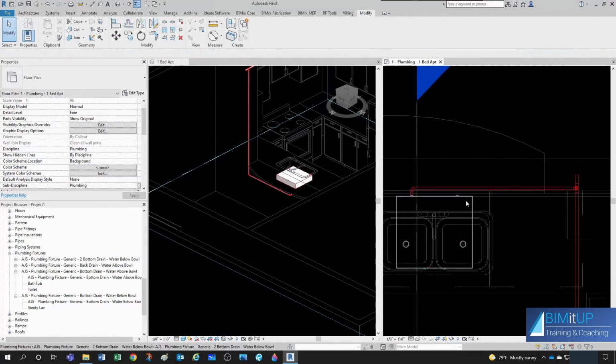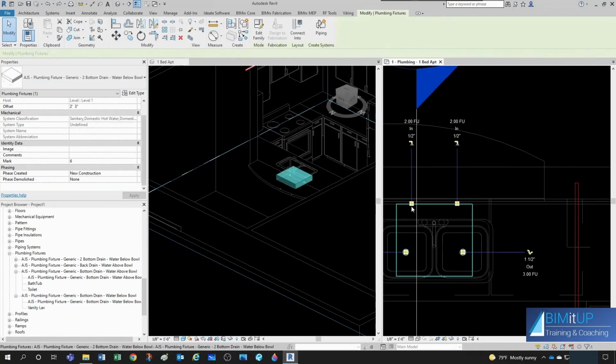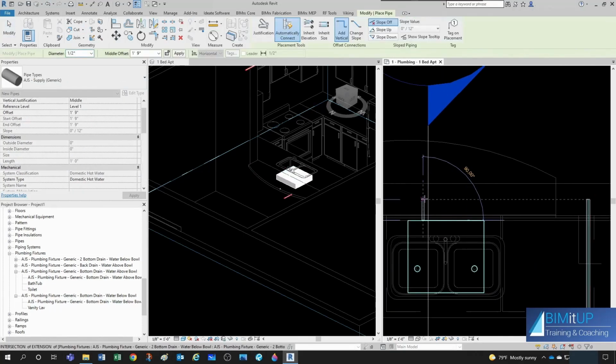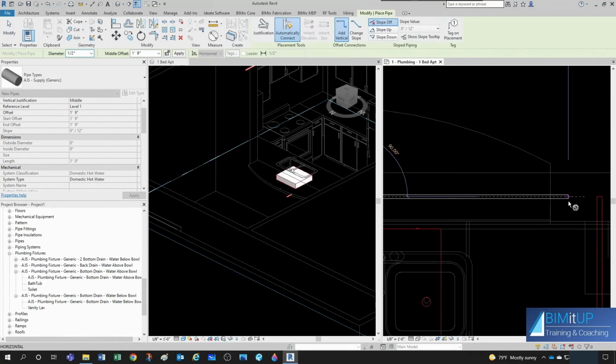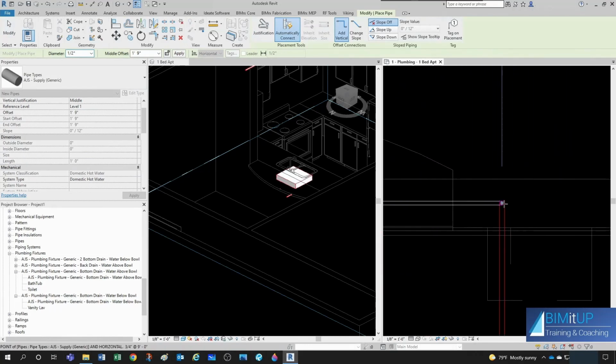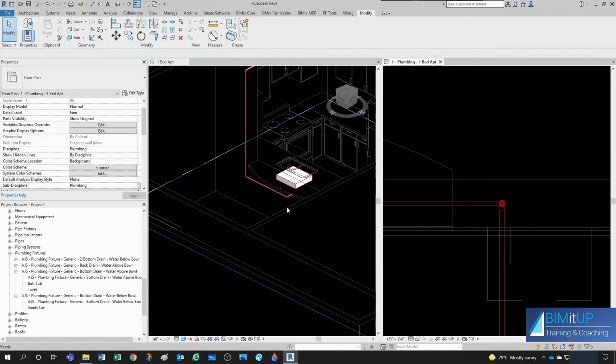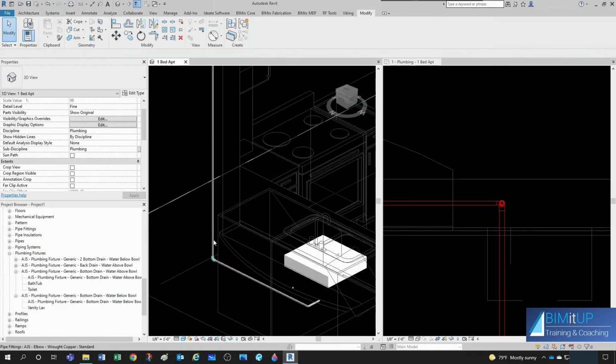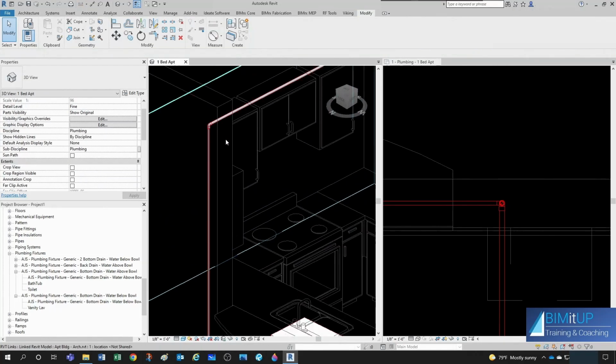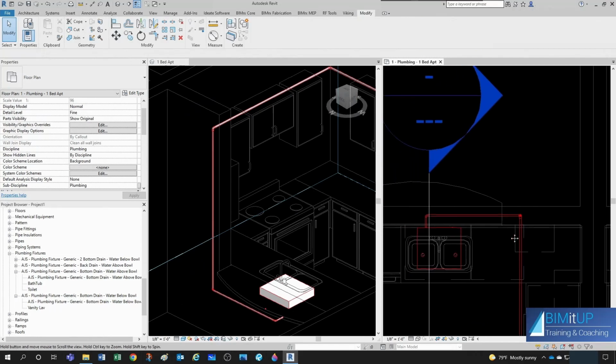And then Revit will give you a bunch of different options. But most of the times this is not necessary. I can simply just eyeball it. I can come like this. I know that this is my hot water, so let's get out of here like that. And see, I could come like that, and it will make the connection for me. It was not that bad. I don't need any automated routing or anything. I just want to be able to control my destiny, right?